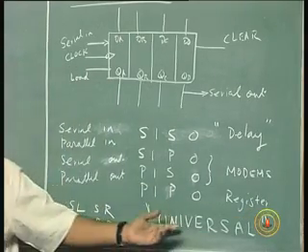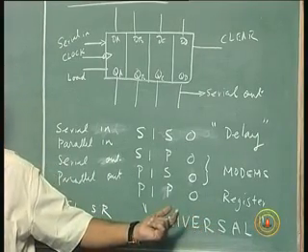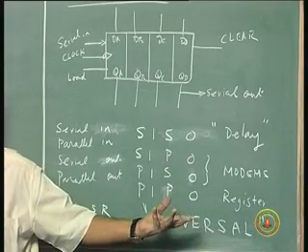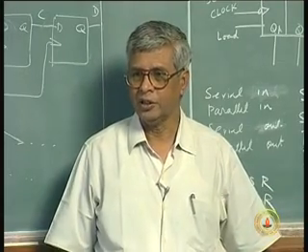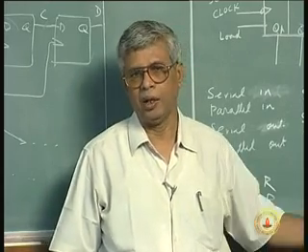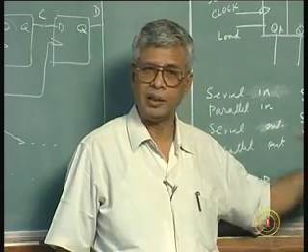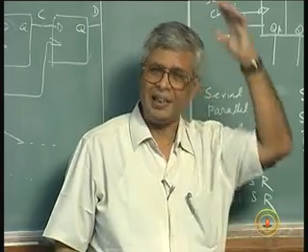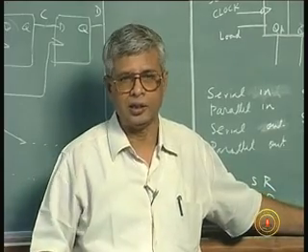Because they can do all the things that you want to, but of course not all of them at the same time. You have to configure it for one particular operation. You configure a shift register for a shift left operation or a shift right operation, or parallel load and serial out, serial in, parallel out, and whatever. These are available in the market commercially, but you should know what is inside. Inside, after all, nothing. So, I have reduced the myth of all these registers, counters, this, that.